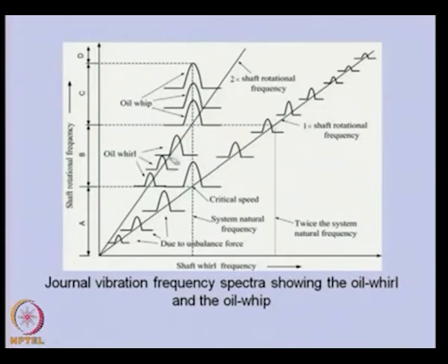we can analyze them only through nonlinear analysis using the Reynolds equation. In the subsequent slides, I will be showing how we can get these amplitudes with the help of the pressure variations in the fluid film bearing. So, I will be showing a glimpse of the procedure, so that if we need to analyze this system, we can see how the Reynolds equation can help us in finding out this particular phenomenon.